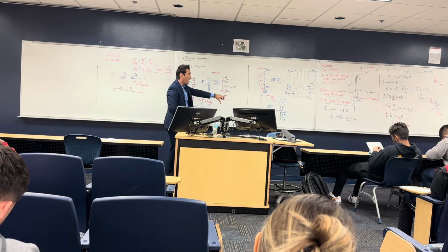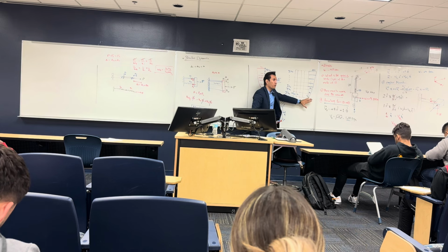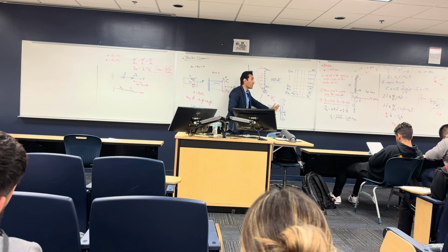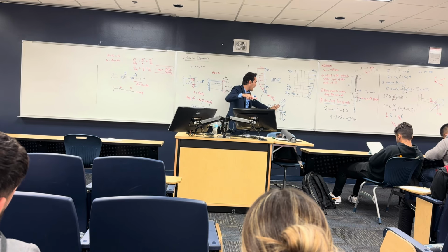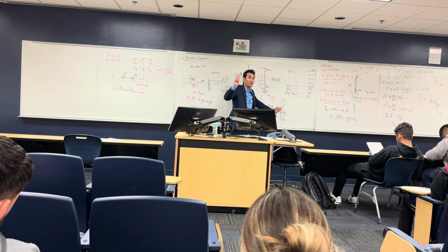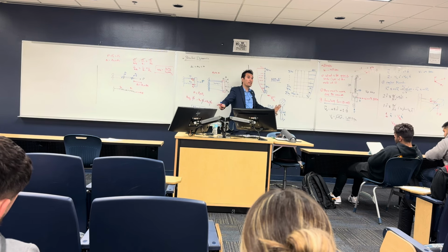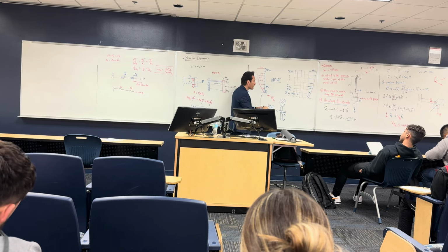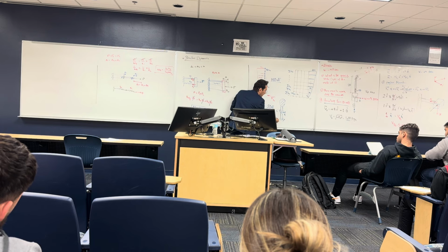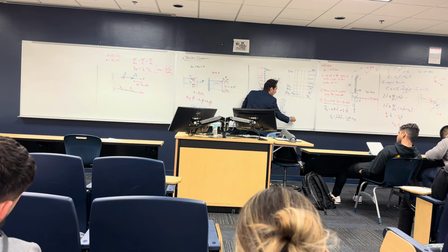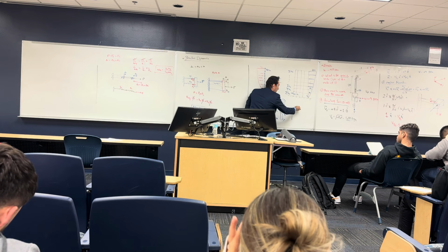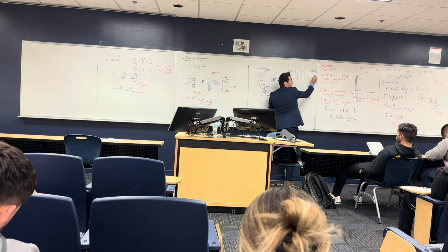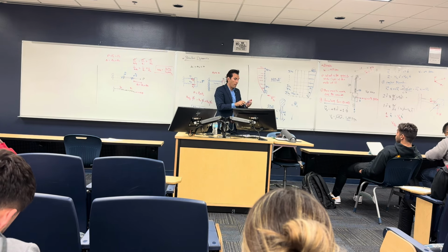All right, so right now I have multi-degree of freedom systems 3D, multi-degree of freedom 2D, and single degree of freedom. That's what we are going to do in this course next time, how to solve a single degree of freedom structure. But there's a thing. Solving this means that you solve the entire structure, not just one degree of freedom, because once you get the delta, let's say this got hit with an earthquake force F, and you were able to get how much displacement this mass is going to have, this delta actually is this delta. So you got the delta for your entire structure.